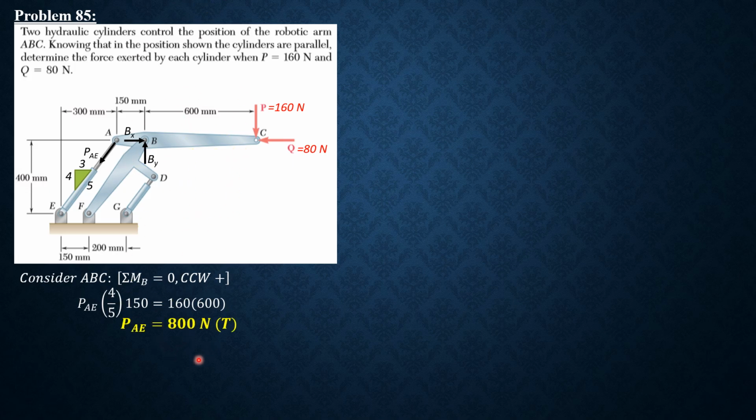800 newtons tension. Now we will not touch that. These are internal pins, so we transmit the 800 Newton force at E this time. So let's remove these forces and consider the free body diagram shown.